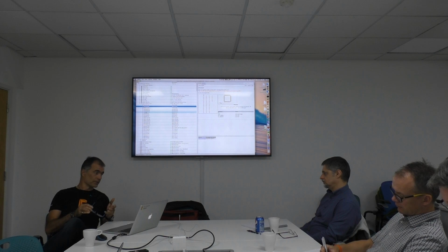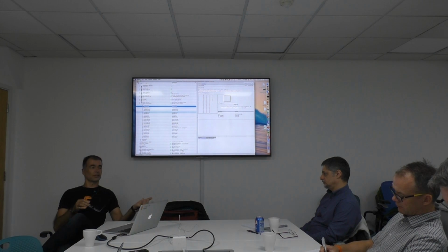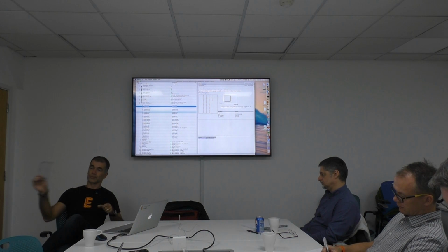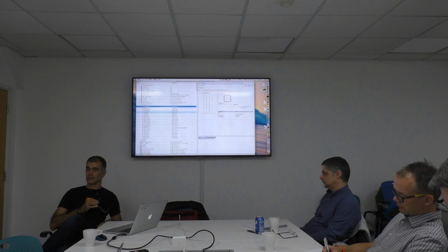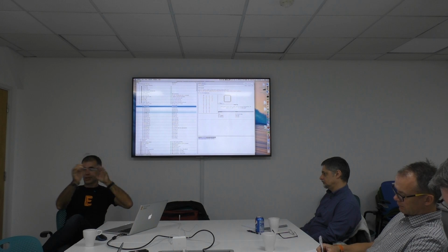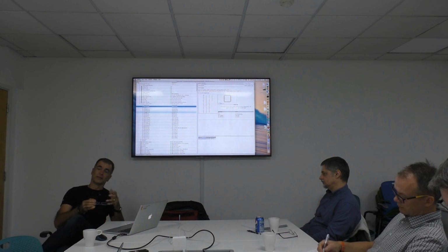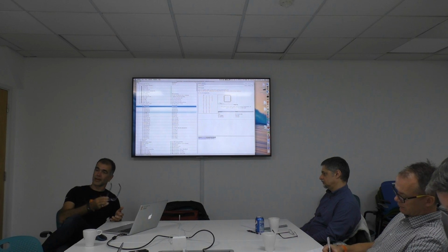Think how you name the stuff, because as soon as you bring such a component into the schematic, the full definition is in the schematic. And everything refers to this library, to this device name, to this symbol name, to this package name, to this 3D model. If you now decide one day later, I have to change the names because I should have named it test 11 but test 12, that doesn't make sense. And then you can rename it, but you lose the connection between schematic and library.